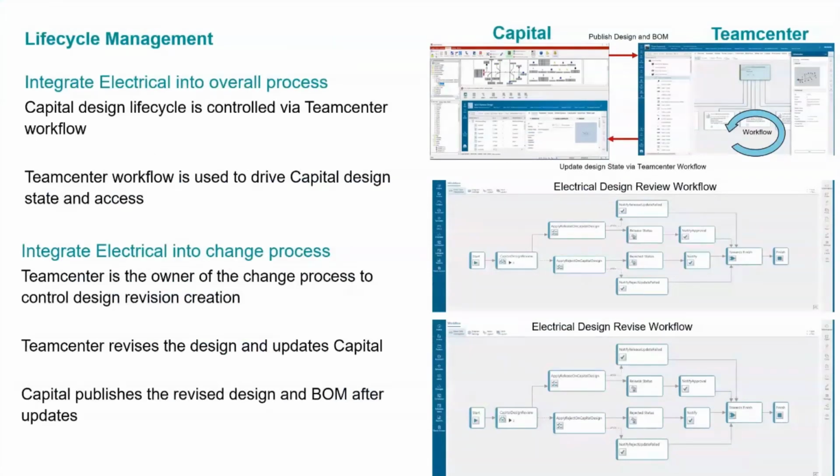And carrying on that theme of Teamcenter managing the life cycle of Capital designs, the integration also supports the use of workflows in Teamcenter. And currently there's two types of electrical workflows available, with example workflows that are shipped directly with Teamcenter. So the electrical design review workflow allows a Teamcenter user to progress a Capital design through an approval process and ensures the design in Capital follows the Teamcenter states to keep the release level on the Capital design in sync with the changes being made in Teamcenter.